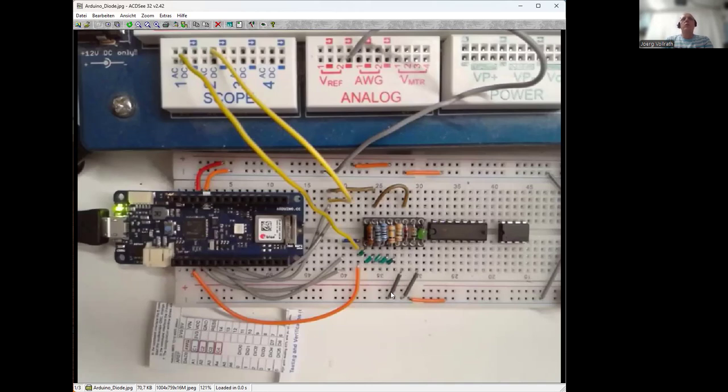So then I expect I can measure a diode characteristic. The voltage will be measured directly at the diode here with our channels C2 and C4 of our oscilloscope, and then my current will be calculated with a resistor and the voltage drop along the resistor. So my current will be the voltage difference divided by the resistance value.